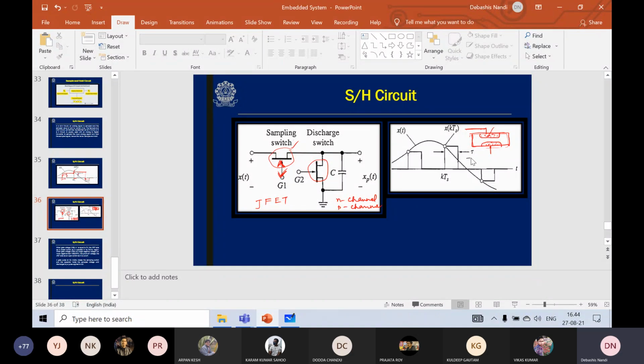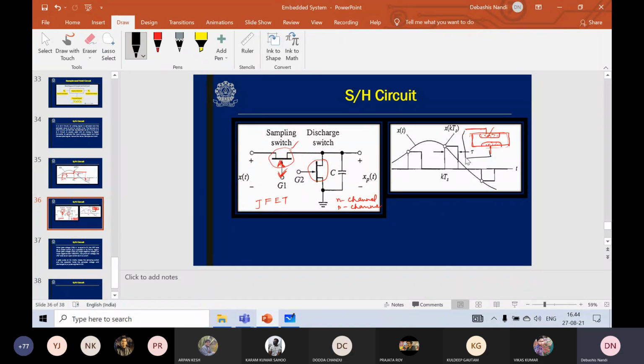Then these two sides will be connected to each other like this by using a conductor wire, and that is actually gate G, the gate of the JFET. Since this is an N-type substrate, the gap between these two heavily doped regions is called the channel. This channel is an N-type channel because these are P plus type. I have taken an N-type silicon substrate. Therefore, this region is N-type, and these two regions are P-type regions.